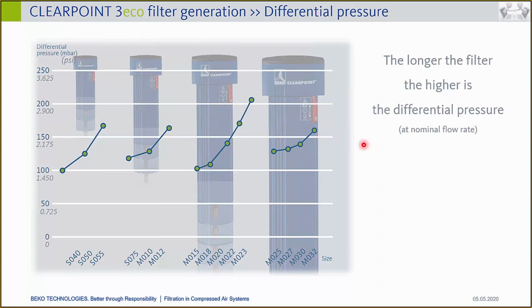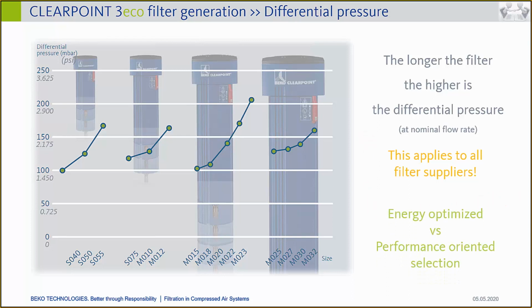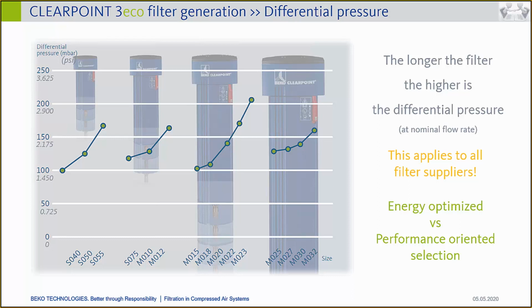This factor that you have an increased pressure drop by longer filter elements is also true for any filter supplier on the market. So as we already talked about, in case of selection process, it depends if you are energy optimized oriented or if you are a performance oriented customer. That depends on what type or what size of filter should be selected. All right.